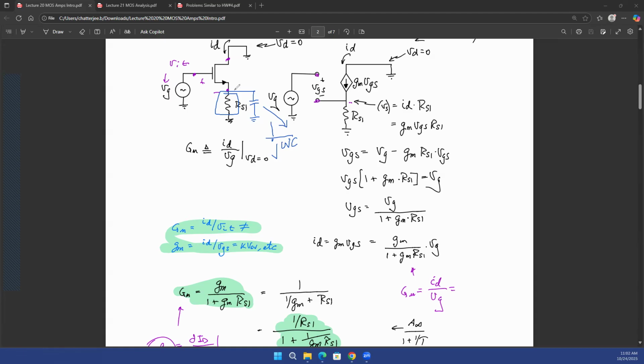So in terms of DC analysis, the analysis that we just did will hold true. If my VT increases, my current will reduce. If my current reduces, my source voltage will go down. If my source voltage goes down, my VGS goes up, and VGS minus VT remains constant. So the stability in terms of biasing is achieved because your capacitor is an open that does not affect anything.